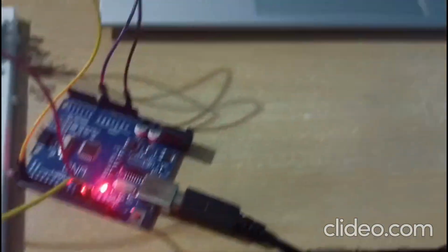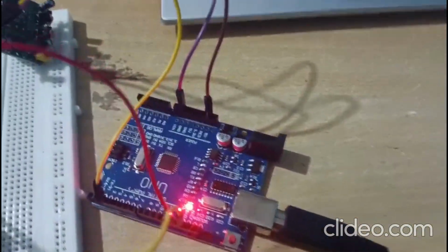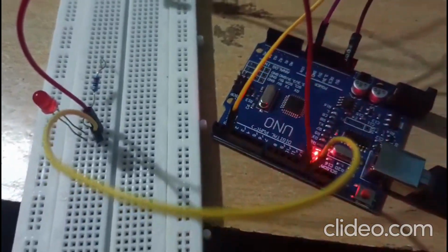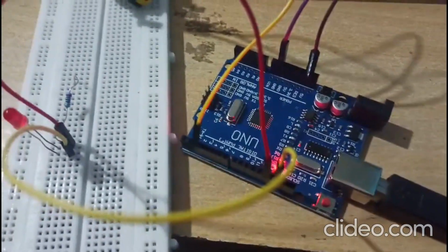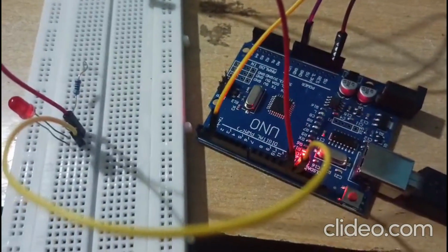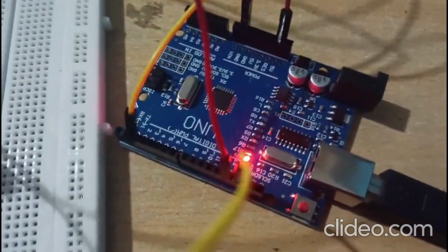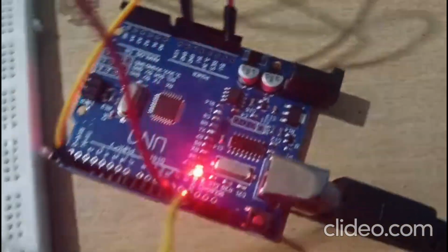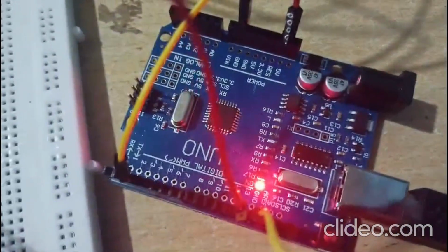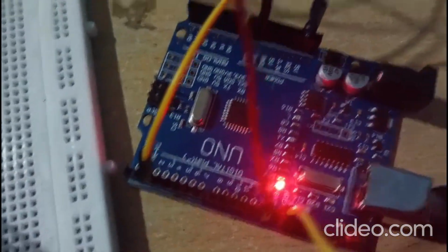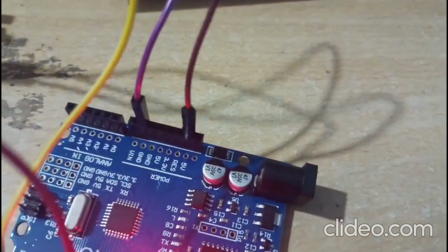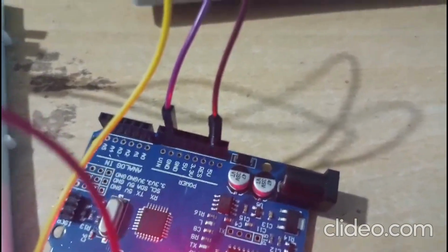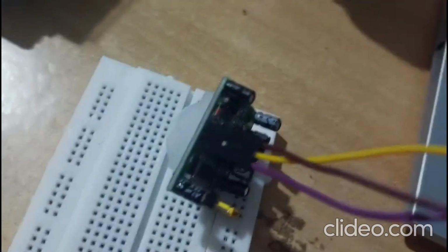Yes, here you can see my Arduino UNO is connected and totally we are going to use 5 jumper wires. Initially my LED is off as no motion is detected. As per our program, LED positive, nothing but red wire, is given to digital pin 13 and negative is given to ground here if you can see. And for sensor I am going to use digital pin 2 and voltage and ground are same as previous IR sensor.